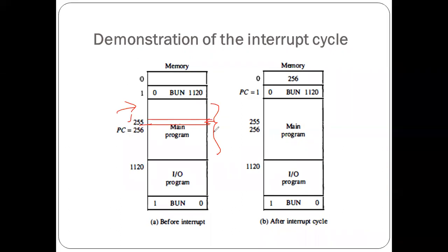It will do so only when IEN is 1. IEN is nothing but the interrupt enable flip-flop. This allows the interrupts to be enabled or disabled. Even if input or output devices need service and set their flag bits, if the IEN bit is 0, the CPU doesn't recognize the occurrence of the interrupt, because the R bit will not be set to 1.